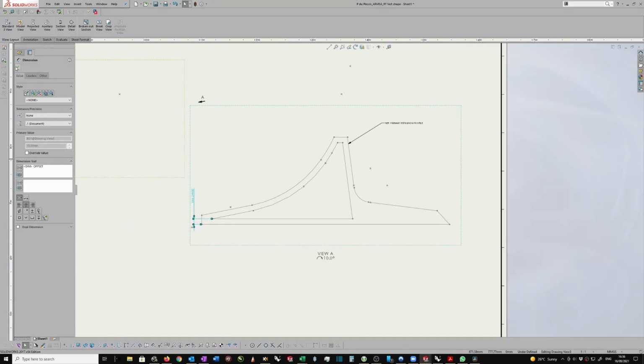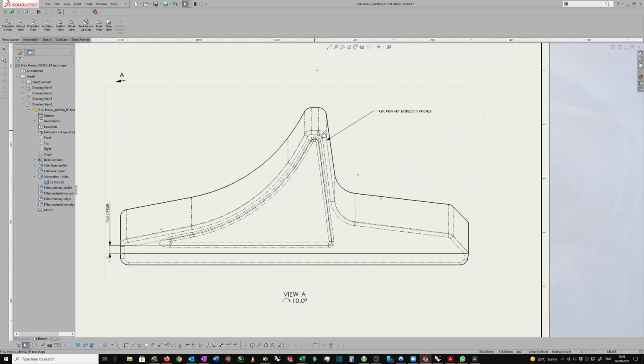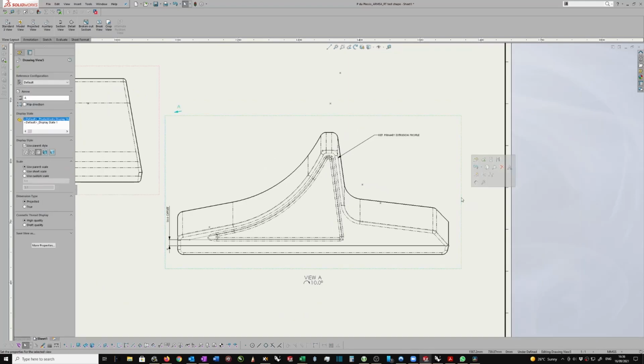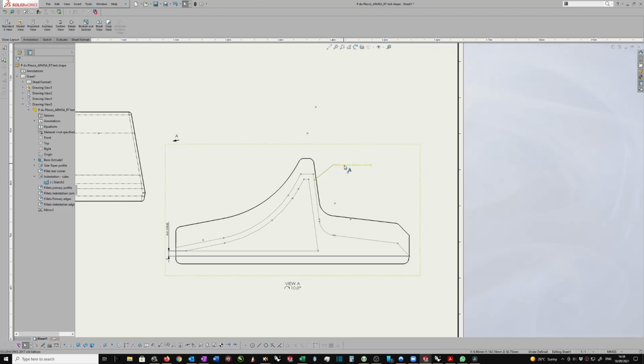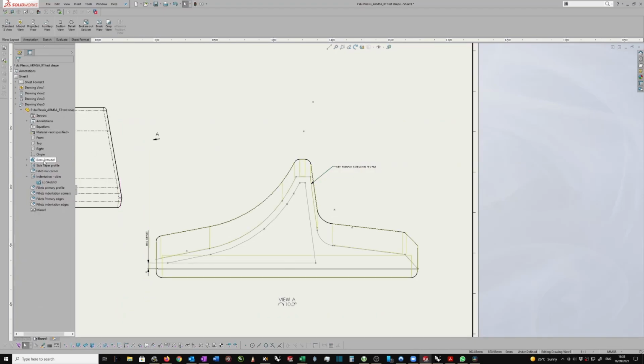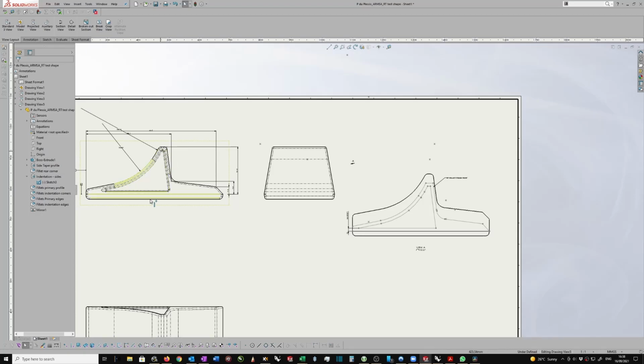And let's just go back. So I think here we'll have to show this feature. This would almost be good enough. I think what I would do here, just to make things clear, is a quick further addendum. So just to make this really clear, I've got primary extrusion profile. You could use the boss extrude here if you rename that, but a better way would be to make sure that you refer to this front view.